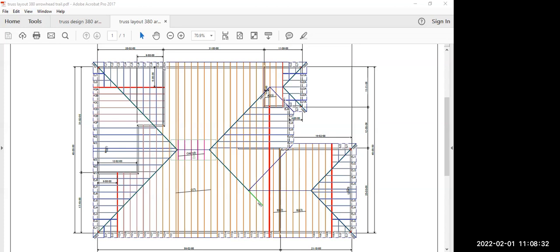Anyway, maybe we'll get a chance to play with that a little bit more, but this concept of a reaction, again, my goal is equilibrium. However much weight is on this house, I want it not to move. So I've got to make sure the foundation's big enough to do that job. Most foundations on houses, just out of curiosity, are only 12 inches wide for a 1-story house. So this pink line you're seeing going around the outside of the house is 12 inches wide, and that holds all normal locations.